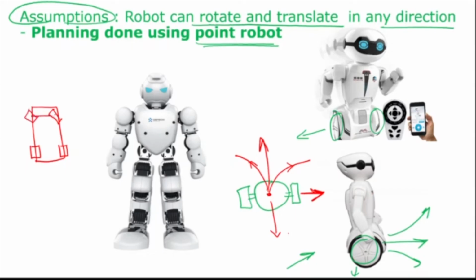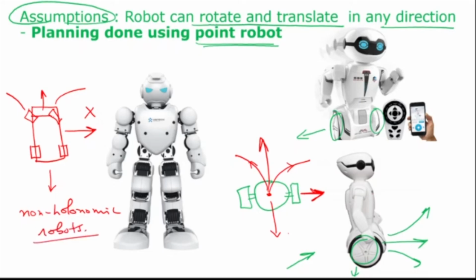Okay, so there is a steering in front. So this car can go front. It can turn at a particular angle. Let's say it can turn like this or turn like this. It can go back. Okay, but it cannot go sideways. Okay, so such systems are basically called non-holonomic systems. And they are non-holonomic because they are subjected to a non-integrable kinematic constraint.